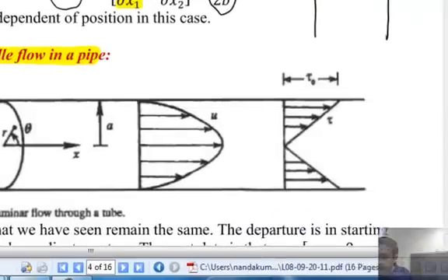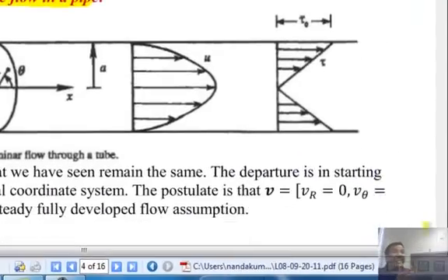So we're going to make similar assumption, but the variation is from Cartesian frame, we are going to go into cylindrical coordinates, cylindrical reference frame. Okay? So we're going to look at the equations of motion in cylindrical reference frame, but other than that, the assumptions are exactly the same. That is, it is a fully developed flow. We are nowhere near the entrance, and so the profile is invariant in the x direction.